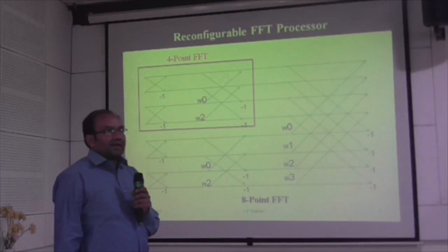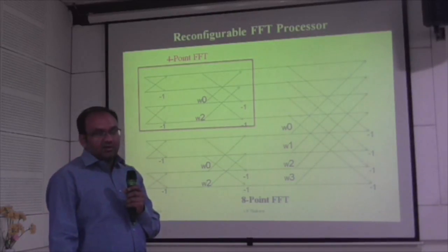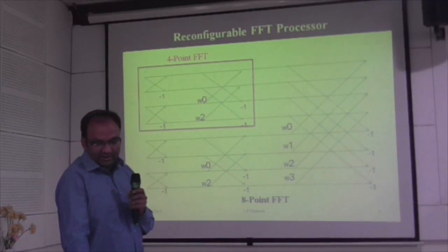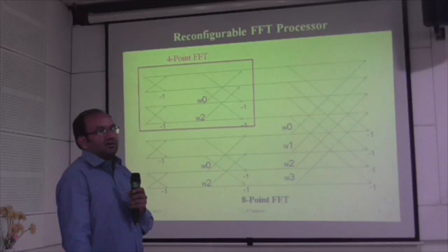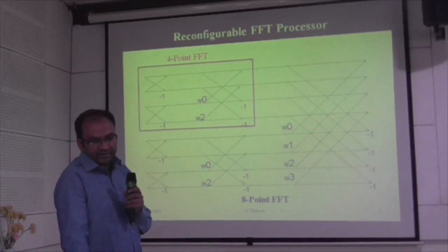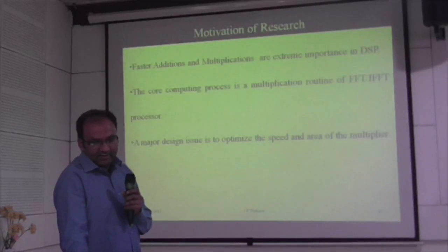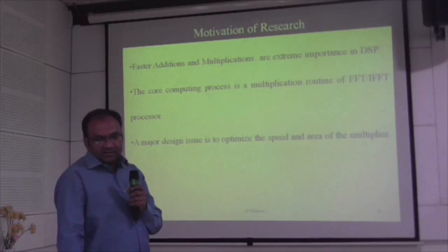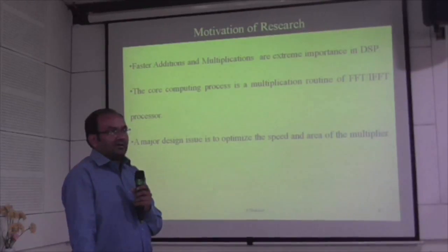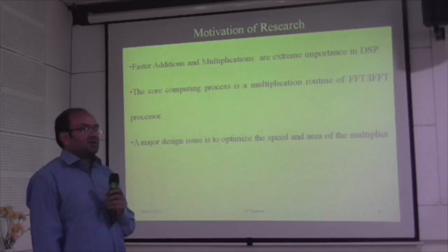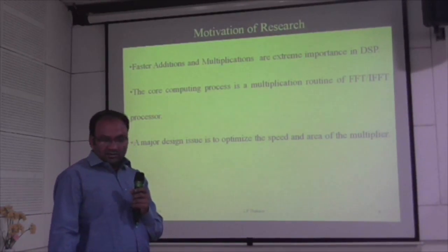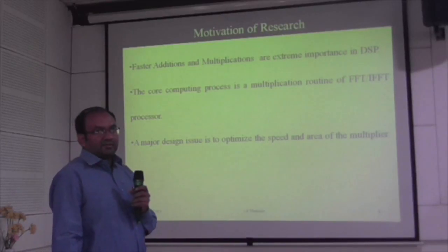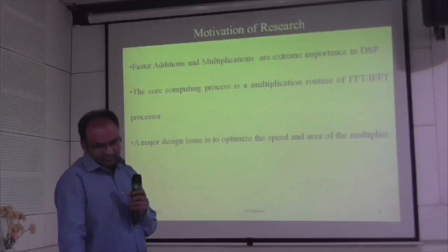So I propose a reconfigurable FFT. What I tried here is to design a generalized FFT form, where we can select any type of FFT. That is what makes it a reconfigurable FFT. The motivation of this research work is to design the FFT and IFFT processor. The signal is multiplied with the twiddle factor, which is a complex multiplication. So I have designed that complex multiplier and used it for the FFT and IFFT processor.